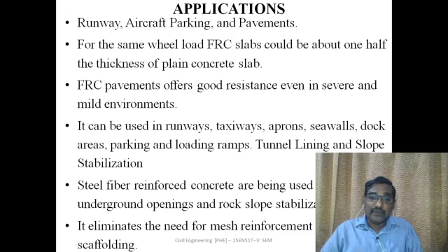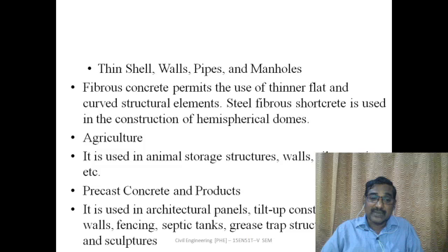Steel fiber reinforced concrete is being used in openings, rock slope stabilizations. It eliminates the need of mesh reinforcement and scaffolding, thin shell walls, pipes, manholes. Fibrous concrete permits the use of thinner, flat, and curved structural elements.